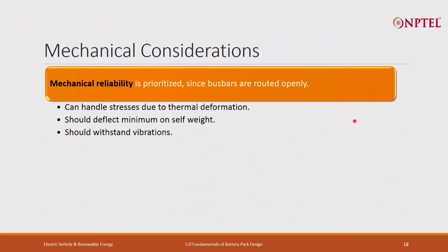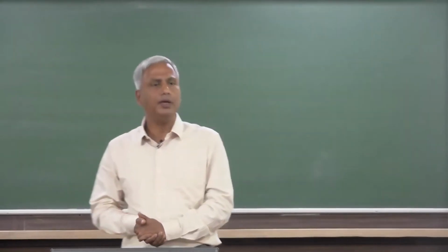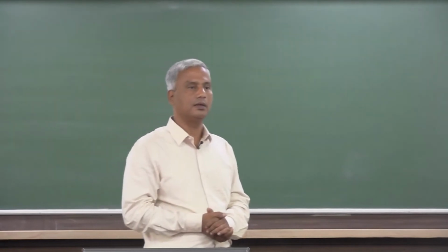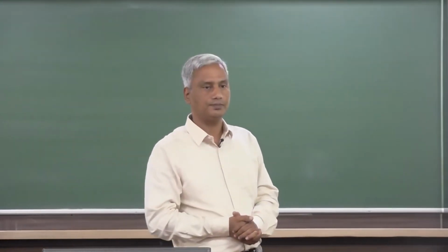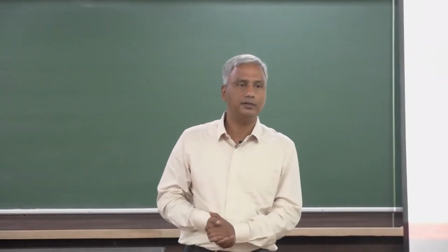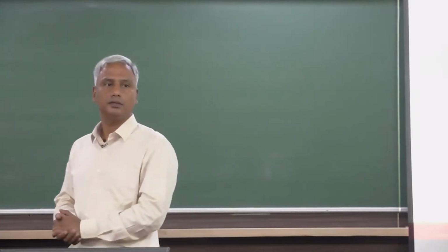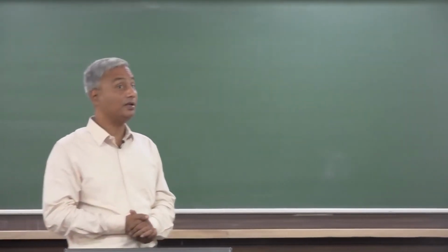Now, if you keep on increasing the thickness, its weight keeps on increasing and it starts deflecting because of the self weight. So, you also have to worry that it should not deflect or bend because of its self weight. It should be able to withstand the vibration which it will encounter during the running conditions and during the transportation.